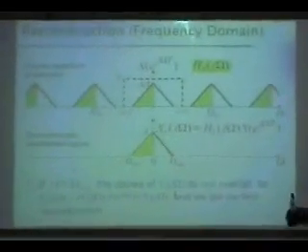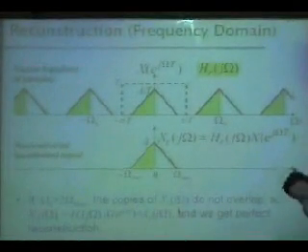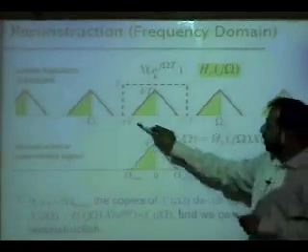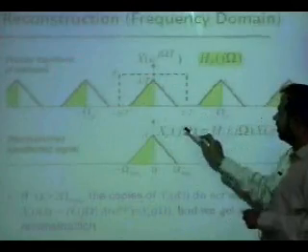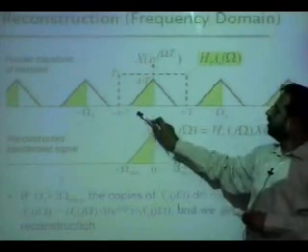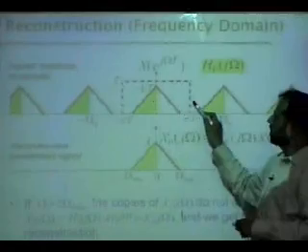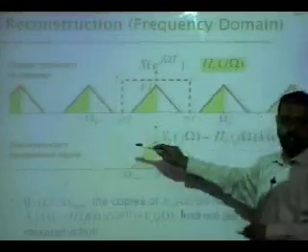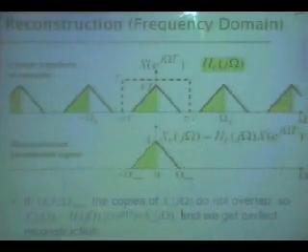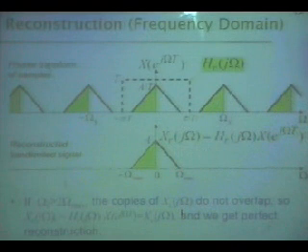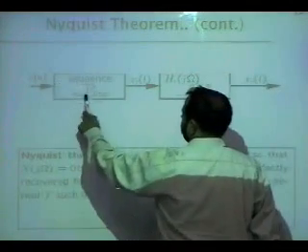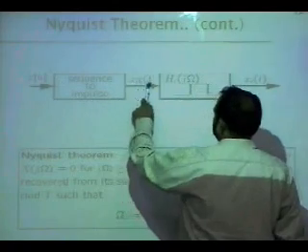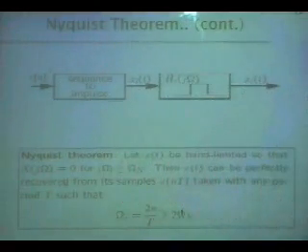So now we are saying, okay, this is the process of reconstruction. You throw the time back. Throw the time back means dividing by T. Then you pass it through a reconstruction filter with cutoff frequency pi by T, minus pi by T, and magnitude capital T. This will eat up all the copies and will get you the signal, the original signal from where you started. So this is the process. You go from sequence to impulse, and then the reconstruction filter will give you the reconstructed signal.